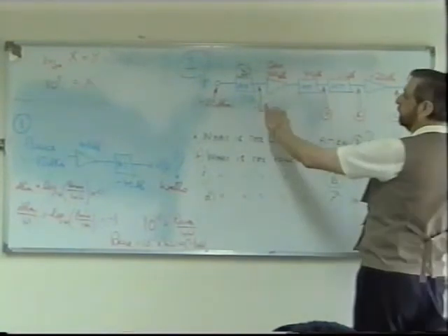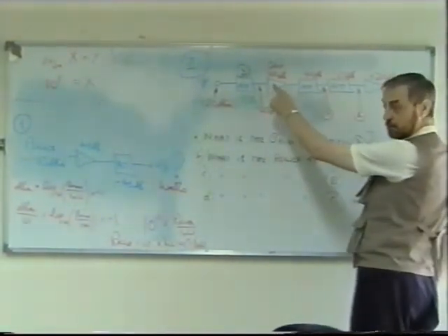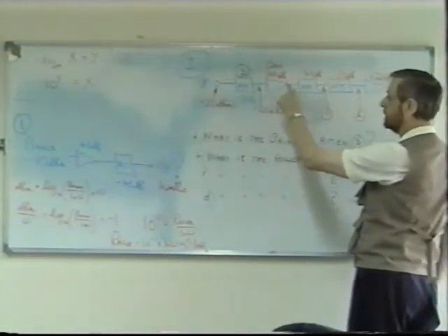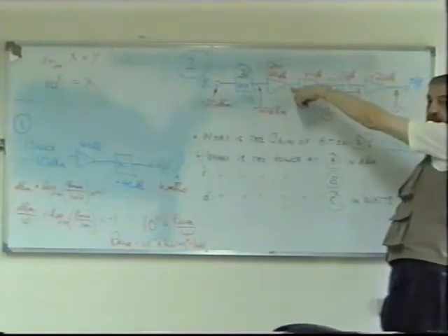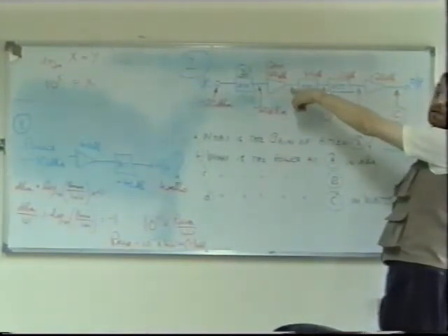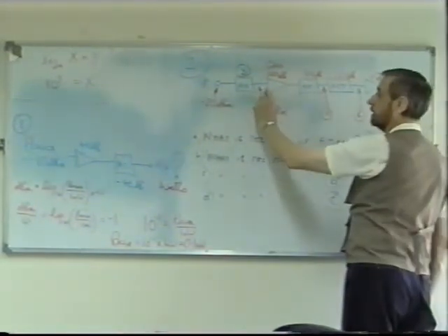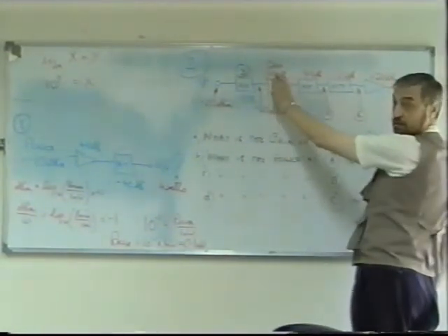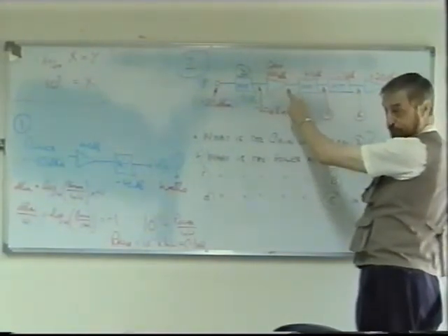Well, we begin with minus 30 dBm, then we go through an amplifier of 100 dBs. So what is the power here? 70 dBm, yeah, exactly. Begin here, minus 30 plus 100 gives us plus 70 dBm.